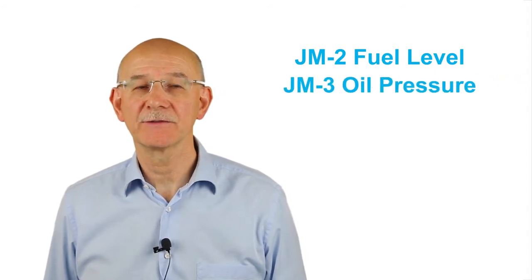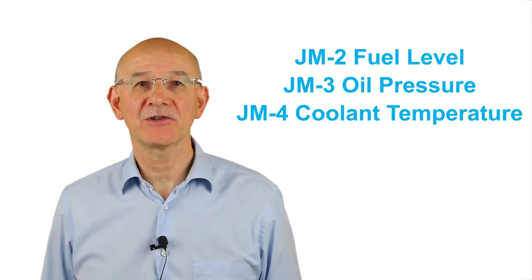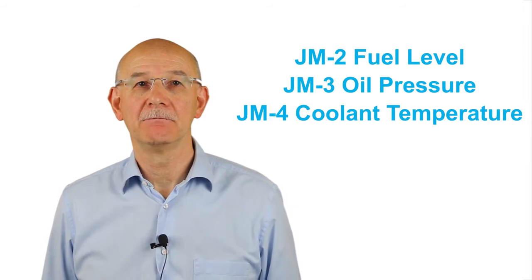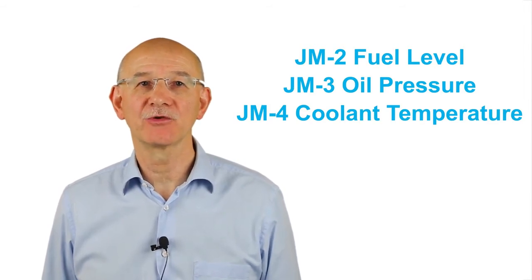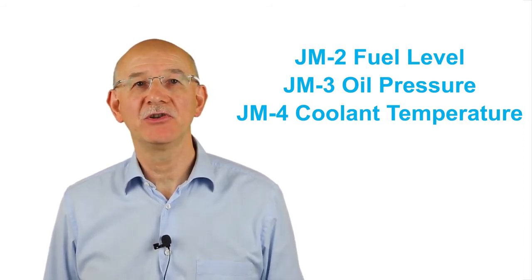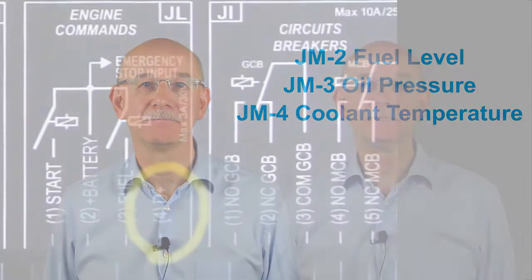If used, the engine sensors should be connected to these 3 inputs. They can be configured for standard VDO sensor or with a custom configuration curve. Later we are going to see how to use them. Resistors up to 2 kΩ can be measured. Depending on the input, the analog measure function can be changed selecting another one from an alternative list.